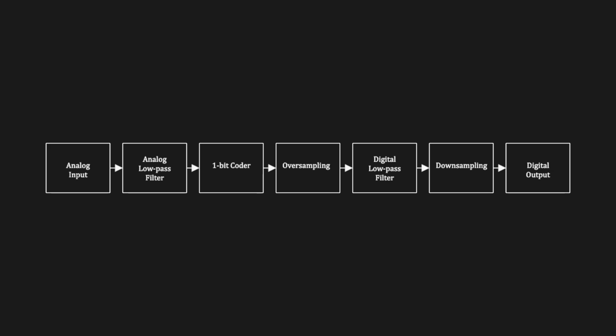Oversampling converters work by sampling the signal at a much higher rate, often 64 or 128 times 44.1 kHz, and using a sigma-delta modulator to process the signal. This high sampling rate allows even short word lengths, one or a few bits, to achieve very fine resolution. The sigma-delta design also performs noise shaping, which pushes most of the quantization noise outside the audible range.